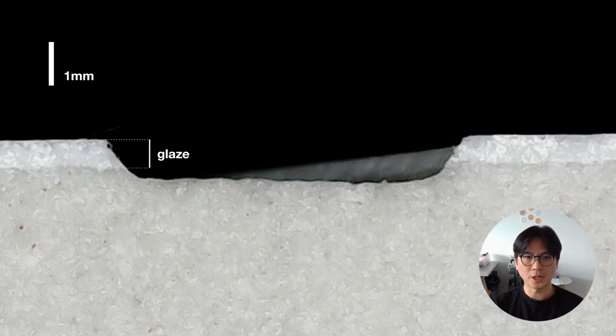Sandblasting removes the top glaze layer, exposing the bare ceramic body underneath. Ceramic glaze is usually a glass-like coating that is glossy and smooth, while the unglazed ceramic usually has a rough and slightly porous texture. As we observed these different textures, we saw an opportunity to use resist blasting to define circuit patterns on ceramic objects.